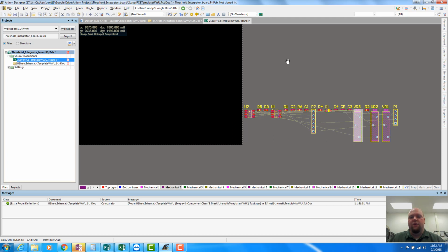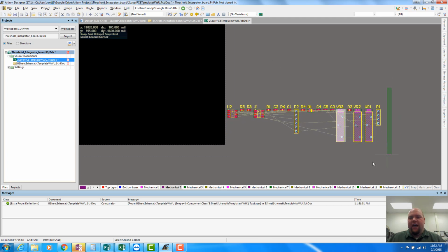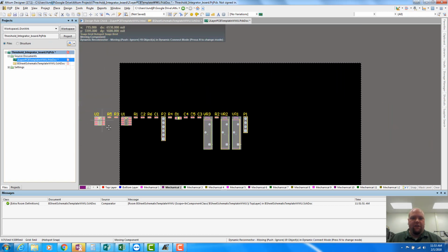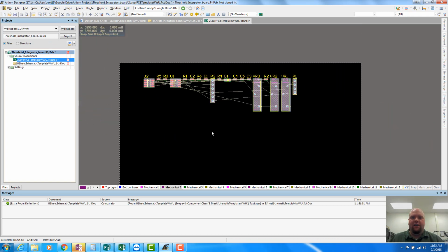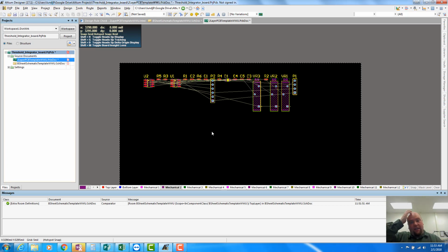We're at the stage now where we're just trying to get these parts onto the board and roughly get a shape for this board. A lot of times I don't want to box myself in right now. I don't want to set a size of a board because I don't really know how big this board's going to have to be. But maybe I can be a little reasonable and move the big stuff into position and produce one board edge, and just use that board edge for now as a reference. Then I can start adding the other sides of the board later on.